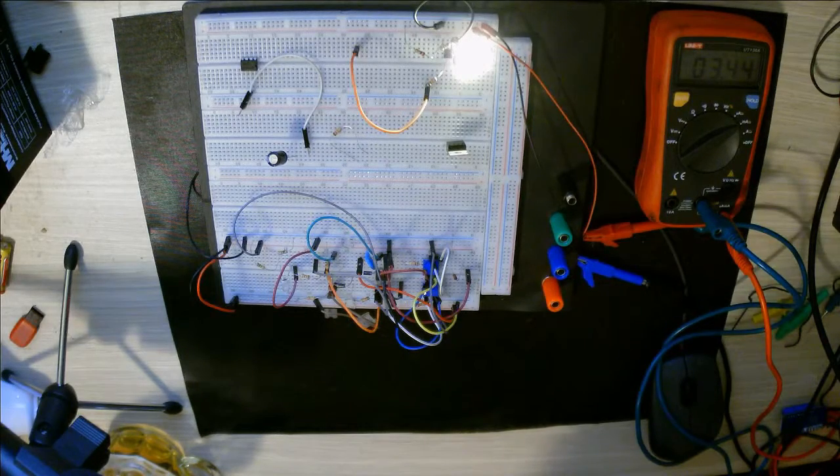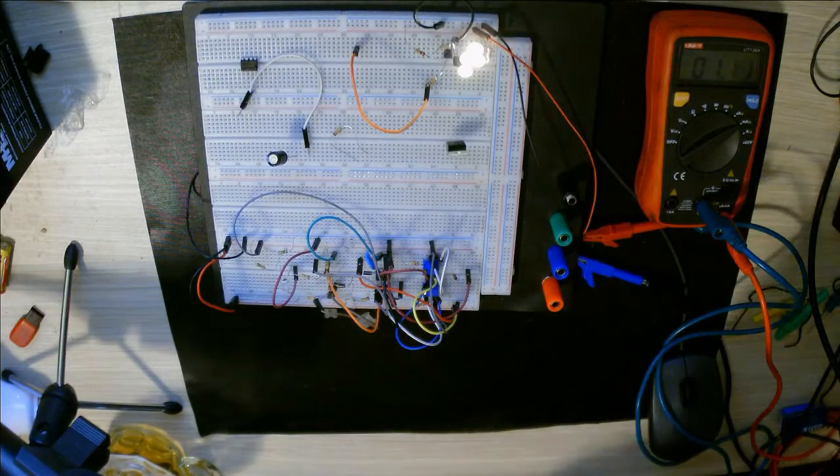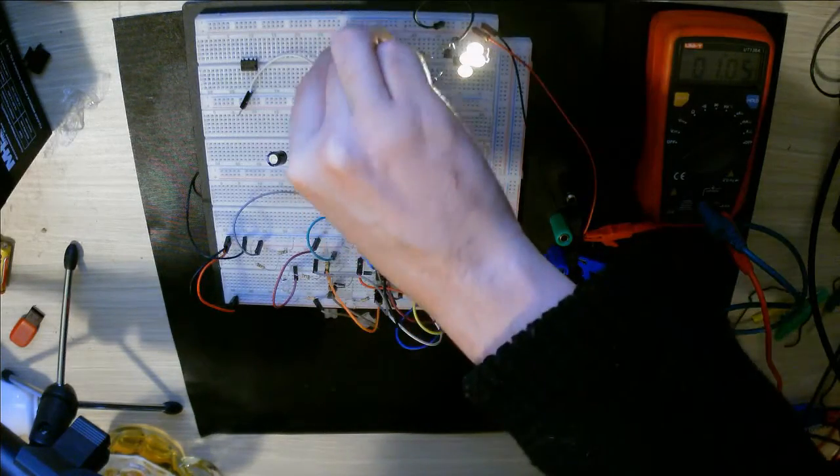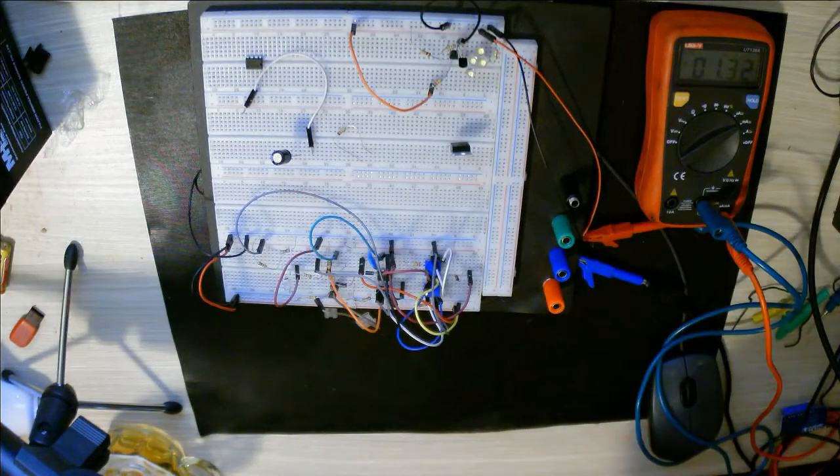Not necessarily the most ideal. 11 volts, we're down to 2 milliamps. And at 10.5 we're down to 1 milliamp. So under these circumstances, the battery's just charging at 1 milliamp, which isn't really too bad. And the other thing to notice, if we turn it on, it actually draws slightly more current. So what that amounts to is,